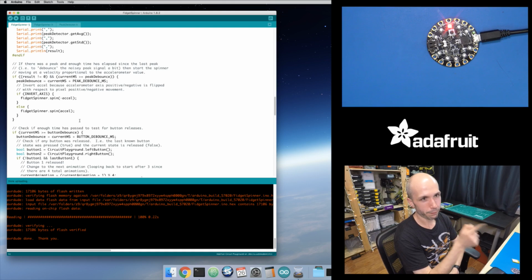And we get the same thing when I flick the fidget spinner. I get the vibrations of the board, and so I get that big initial impulse, but then I get a reverse impulse the other way as it vibrates back. So I said, let's just, after I detect a flick, ignore all the other flicks for the next 500 milliseconds, which makes sense because I can flick it, and half a second later I can flick it again and it'll detect that flick. So that removes some of that noisiness. The problem would be if I didn't have this debounce, I could flick it and it might catch that initial flick, but then it's also very quickly going to catch the vibration or the reflection back. And so it'll start moving the opposite direction than you expect.